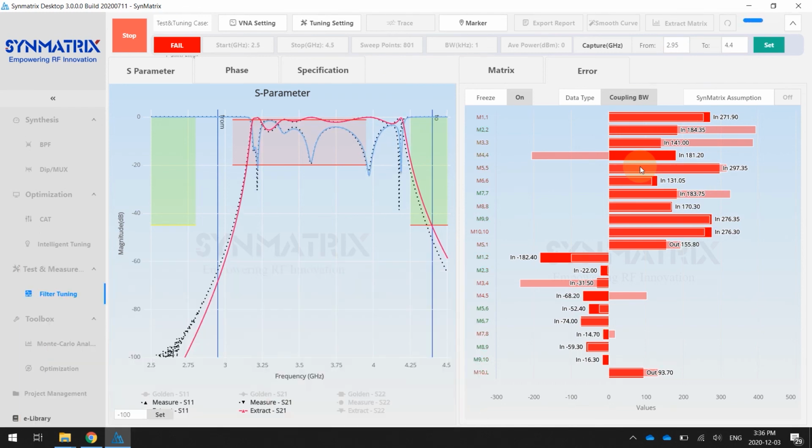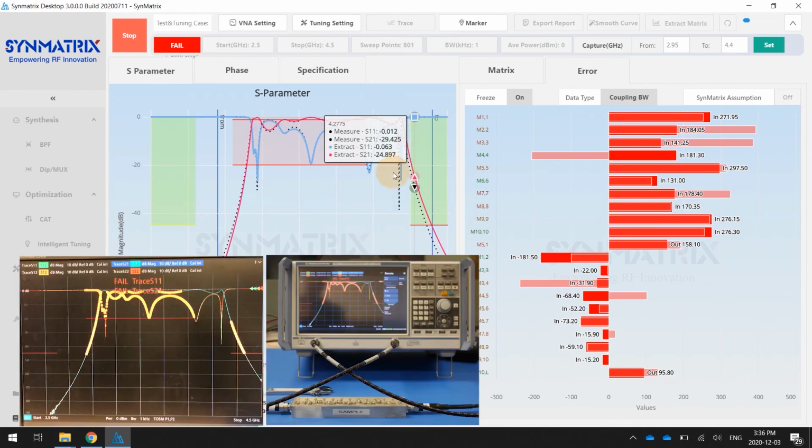As you can see, we almost have the filter shapes. So just keep tuning on these frequency information, because after the assembly work, probably the most critical part for the filter performance is the frequencies. So the user needs to figure out the frequency first, and then focus on the coupling information. Starting from the frequency still in,